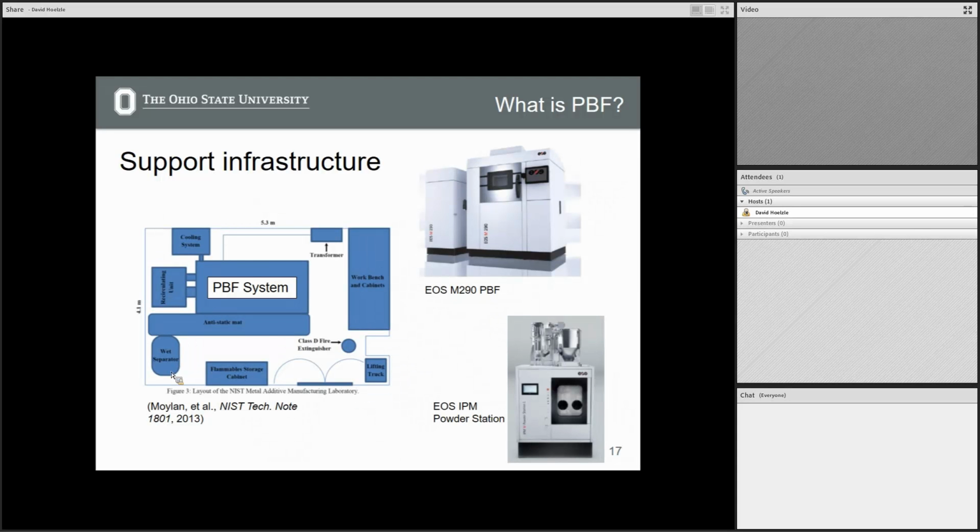All right, so these are fairly dangerous machines. They have, of course, flammable storages. They have wet separators to make sure you can separate things appropriately. This is a powder removal station. You would take your entire bed of powder and put it in this station, and this is a glove box. Has anyone seen a glove box in a chemical lab before? Basically, you work everything through these gloves, and they can keep the environment in, say, argon, which is pretty inert, or something that's safe. With the polymer case you saw, there was just a person with their hands taking the powder off the part.